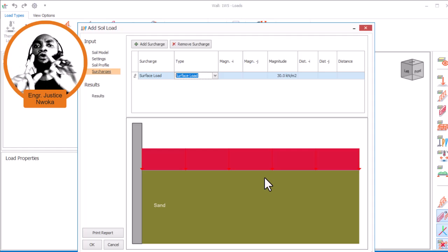And knowing that we design for the worst condition, it is good to use HB load when you're picking the vehicular load. Although when you're designing bridges, we use the two loads, HA load and HB load, for the design of bridges and all that. Even at that, you will see that the HB load, which is for heavy duty vehicles, is what they will consider more to use. Now when it comes to surcharge load, in terms of basement wall or retaining wall, as long as the wall is trying to retain a structure, then you will have to use the HB load.